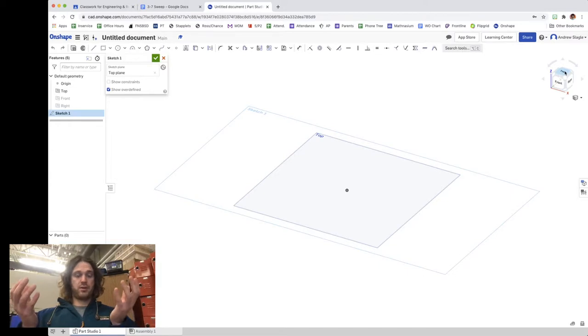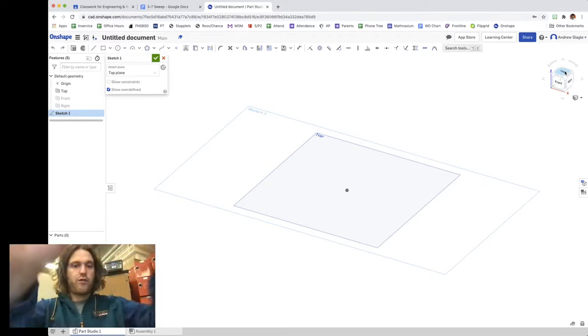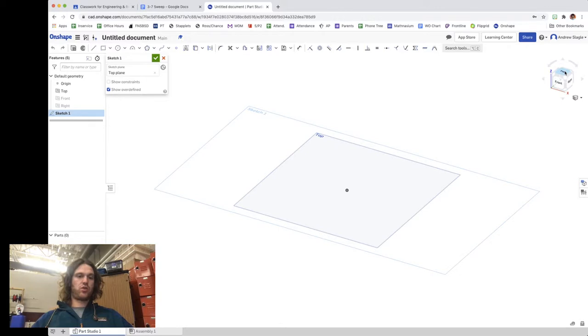You choose a path, some sort of a line or curve, and at the end of that curve you get to draw a shape, and then you get to run that shape down the curve or down the path, and that is what creates the solid. And that can be curved, it can be straight. It's really exciting. It's almost like if you could extrude, but extrude along a path. So that's what you're doing. Basically extruding, instead of a straight line, you're extruding around curves.